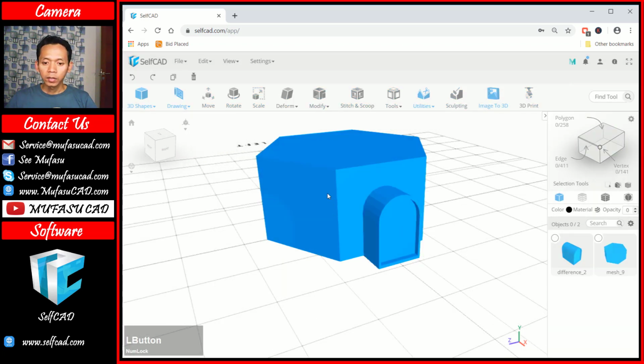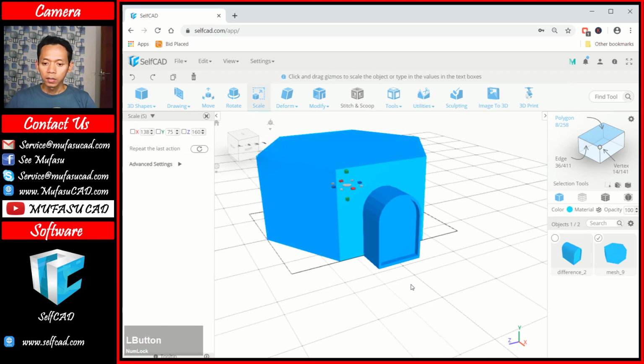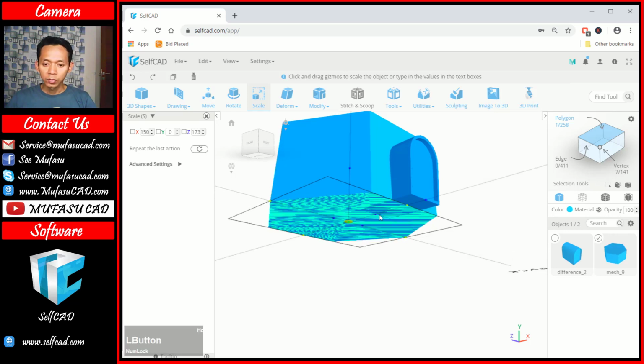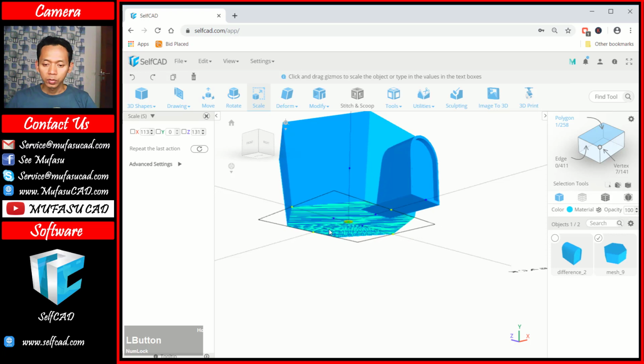I will click at this object, and we can select the polygon option. Okay, you can use a scale command. Okay, I will scale at this face. You can click in here, and we scale to make it smaller here.